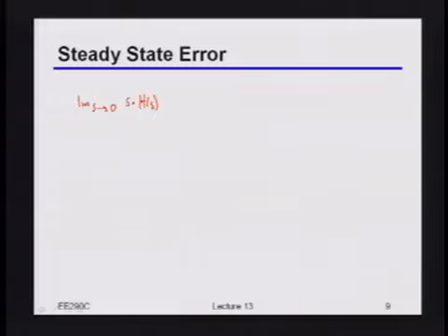So let's see what that would imply in this particular case. First of all, if I have a frequency error, we said that translates into a phase ramp. In the S domain, what would a phase ramp be represented as, assuming I'm working with everything as phi of S?